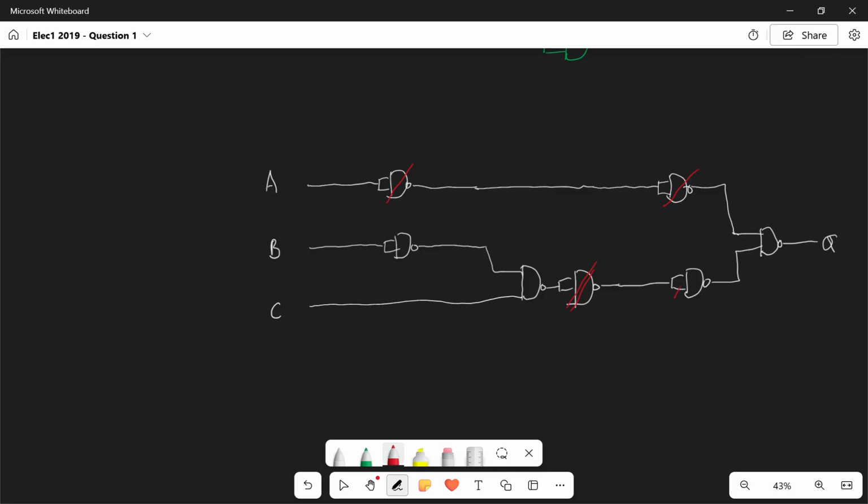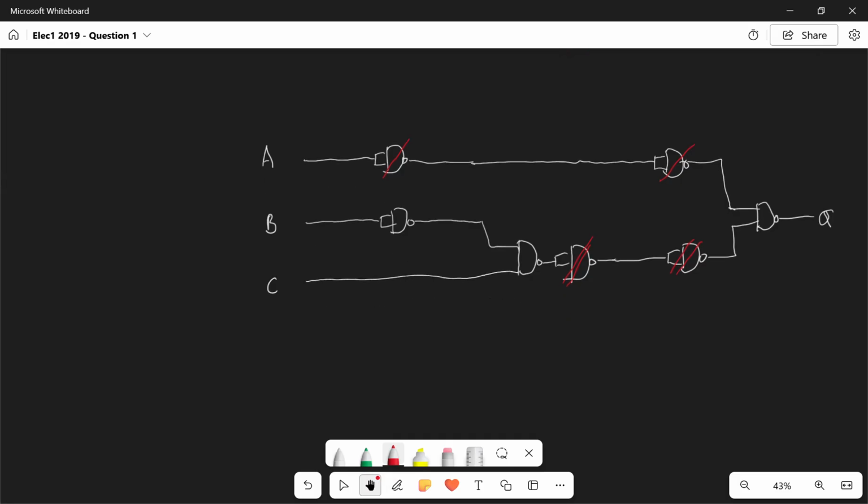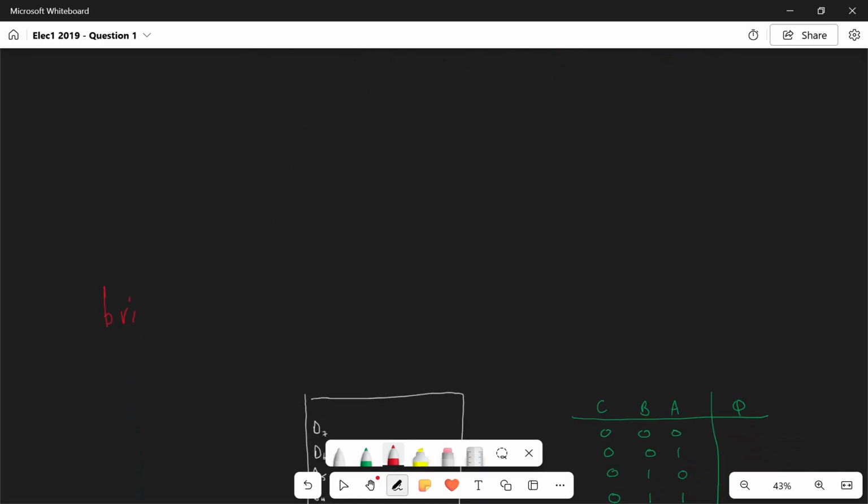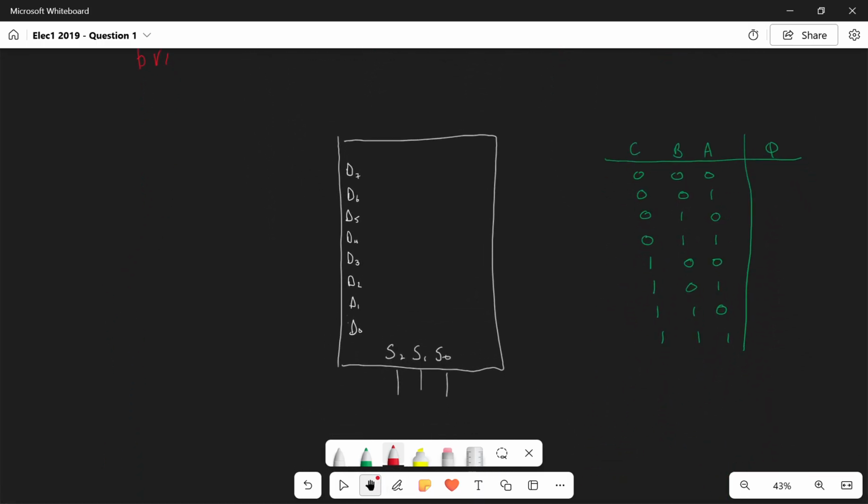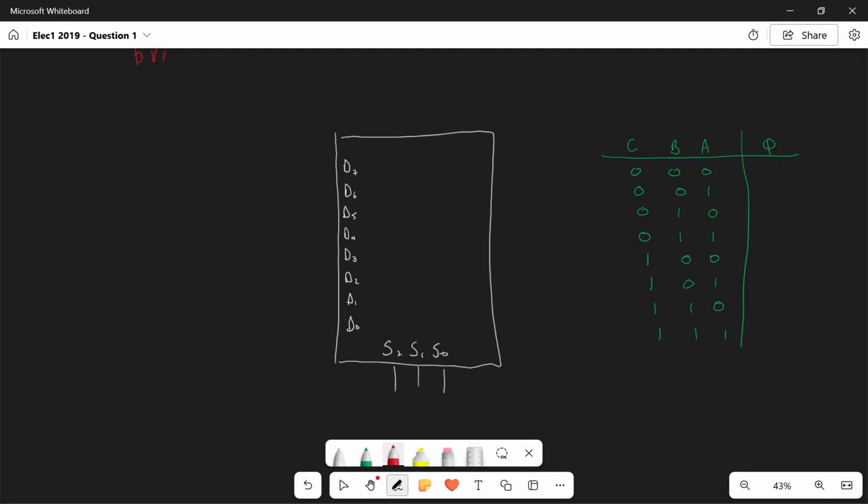And we know we're only looking for 2 because there's only 2 marks, and we show the second pair by giving them 2 lines so that we can see that they're paired and they're not paired with any of the NOT gates above. And then finally, we have a multiplexer. And this multiplexer, the question says, design a circuit that produces the same logic function using an 8-to-1 multiplexer.